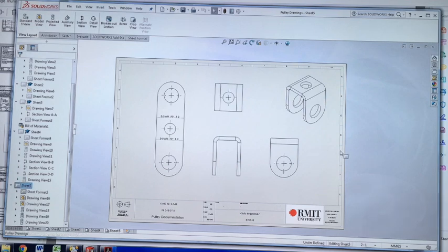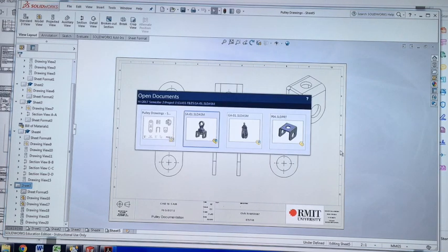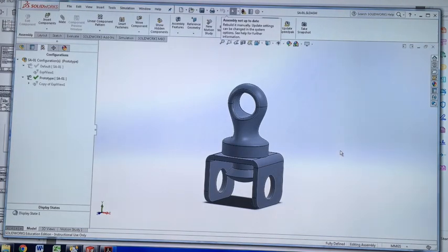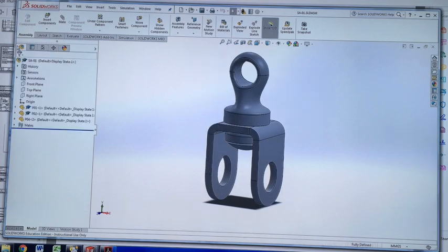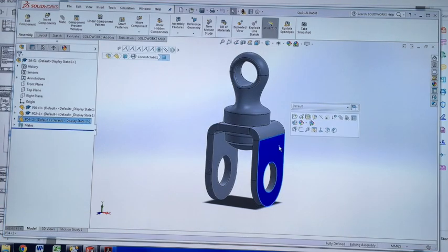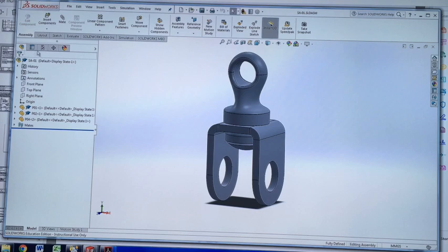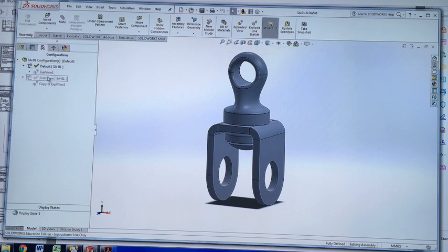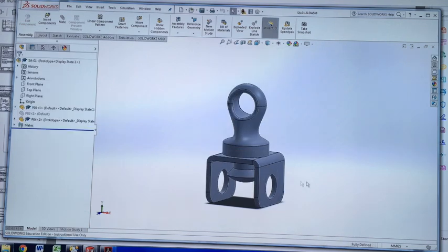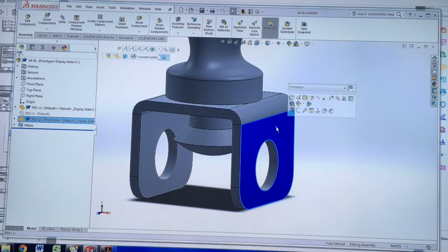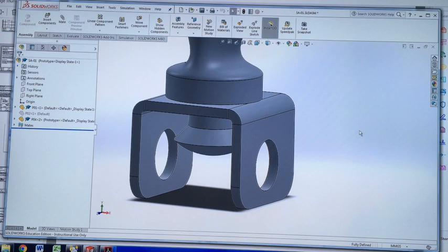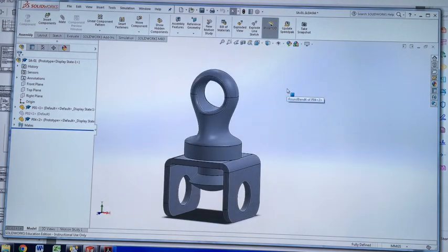Chris? Yep. I just have one question. Back in the sub-assembly, you right-clicked on the part 4 and changed the version. I just missed that part. It seems important. So in the configurations, if we're looking at the prototype configuration and we want to see what the prototype part looks like, click on the part and you should see this drop down. Then you can click on the prototype configuration, press the tick, and it will change it to that version. Okay. Cool.